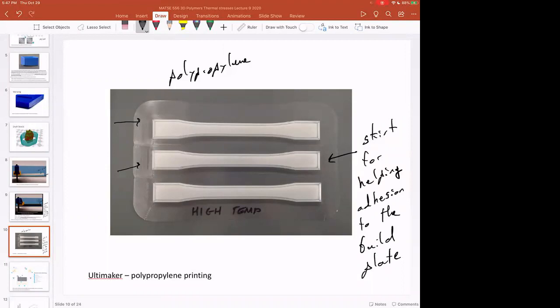And so if you're into hobbyist 3D printing, you know that people use glue sticks or the right type of tape or hairspray or some sort of acetone solution of PLA to hold down their prints and make the print bed sticky. And one way you can increase the adhesion force is to increase the area of the print. And so this skirt helps to glue down the print on the bed. So we won't go into all the techniques.